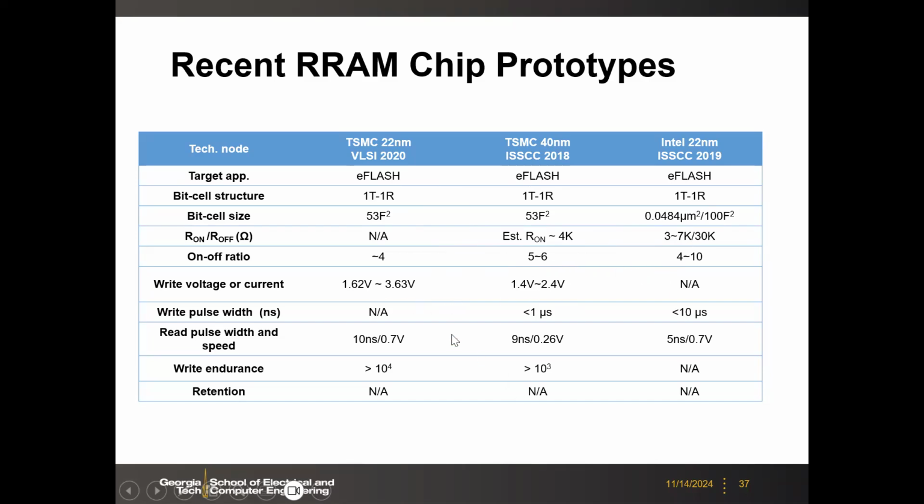And then some of the papers report the voltages, typically below 3 volts, up to 3 volts for the forming, but the normal operation is below that. And then here the rate, a few nanoseconds. Endurance is like, you know, it's like NAND flash. It's not super high. It's not like 1E12, okay?